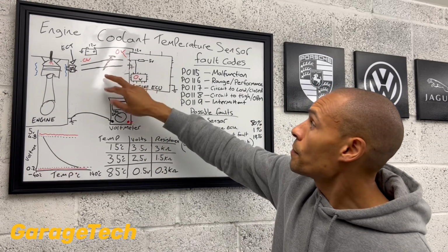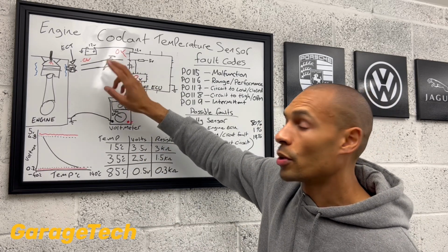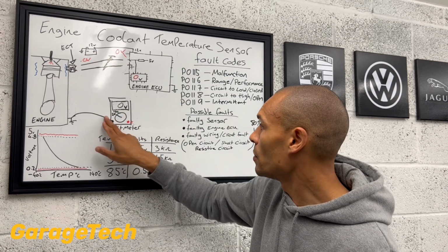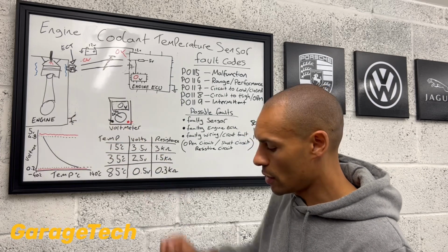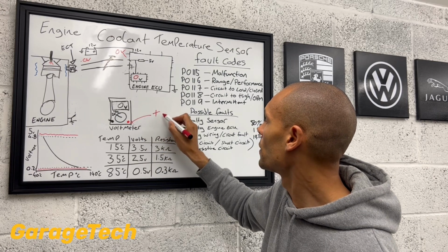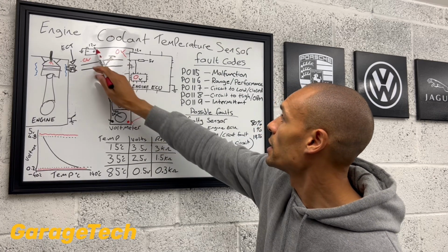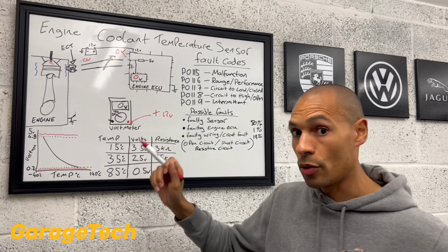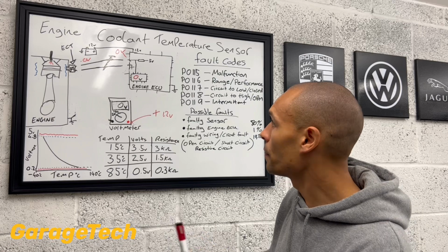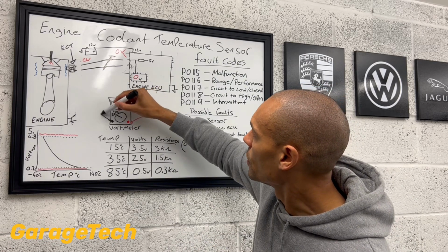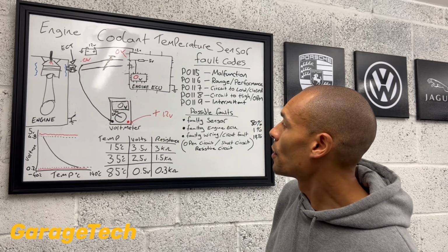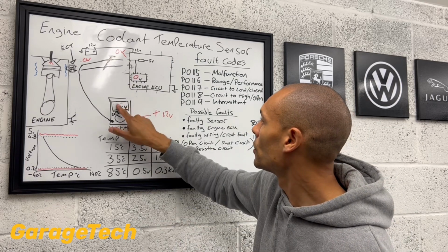Or if that's okay, and it's potentially shorted to the body of the vehicle, then what you could do, and this is a different way of setting up your multimeter, and everyone does it slightly different, but this is the way that I do it. I like to do it this way. I put my red probe on a positive 12 volts, so ideally on the positive terminal of the battery, just depends how long your leads and stuff are. And then I go testing with the black probe this time. You can go to both of the wires, but you might go to that wire there. And then if I've got 12 volts on my multimeter,